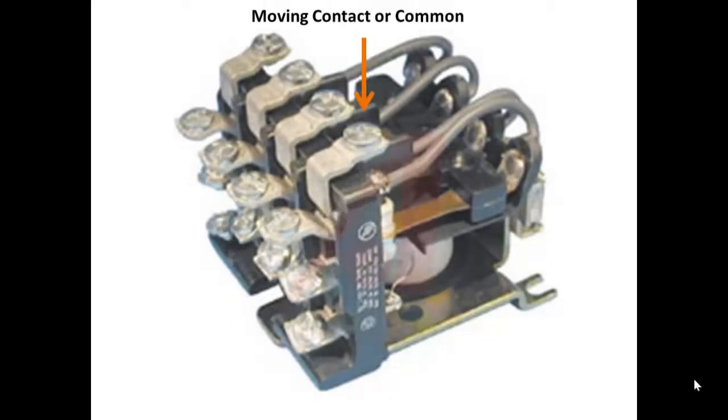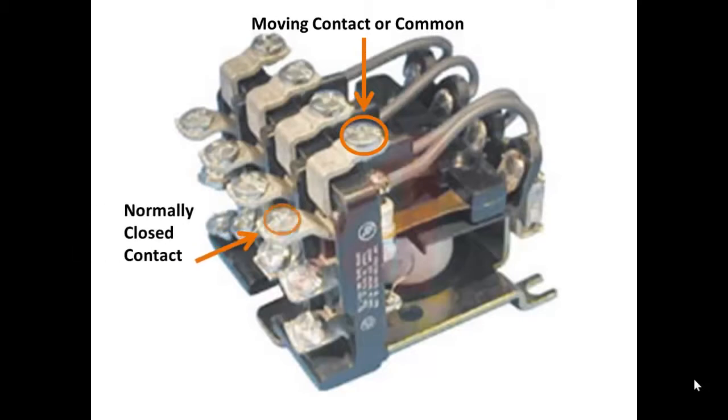And then we've got a moving contactor common, and if you look closely you can see that from the screw terminal you go a little to the left, down, and then back to the right to a black conductor that goes all the way over the other side and then rotates back and then into that copper blade you see there. And you can see the upper and lower stationary contacts, and you can see the screw terminals that they connect to, the normally closed and the normally open.